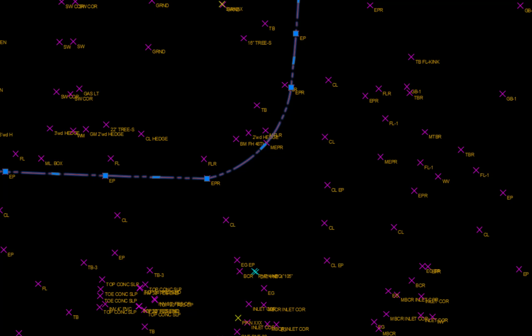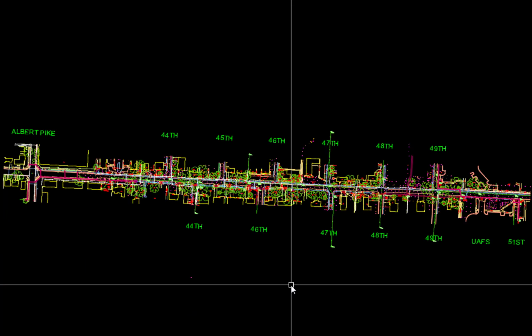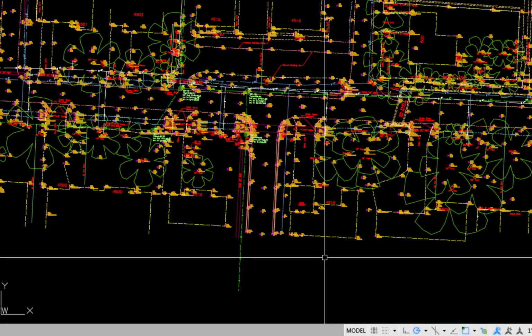During the performance of the drafting work, periodically save the temp topo drawing. For the purpose of this video, the completed temp topo drawing for the Kincaid tutorial project is shown. After completion of the existing topo drafting work, freeze the survey point layers.